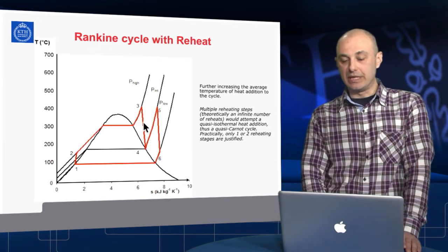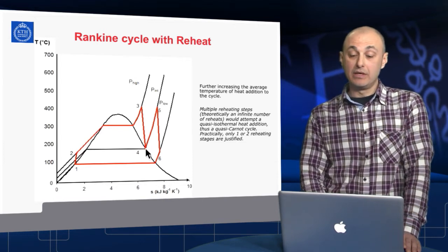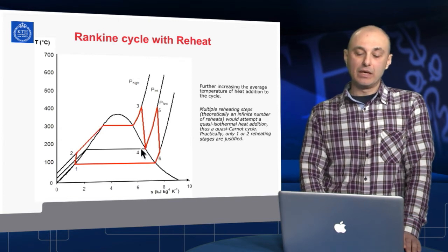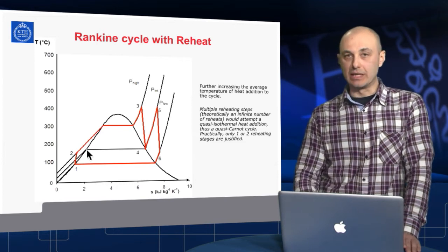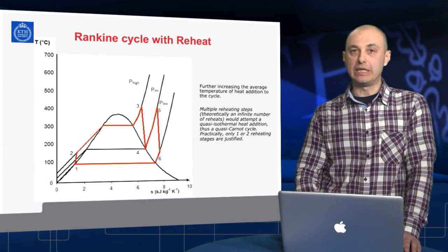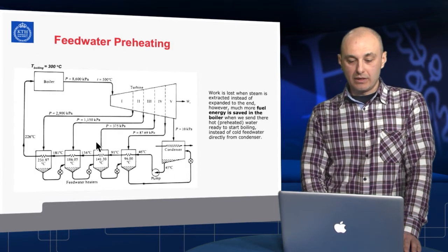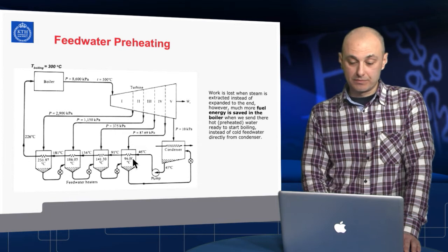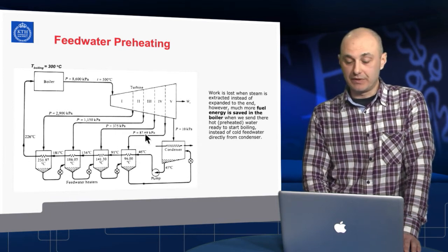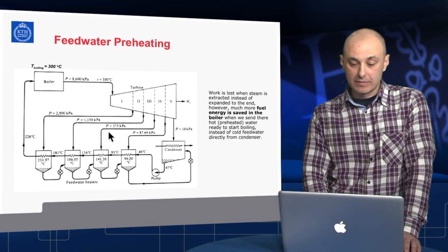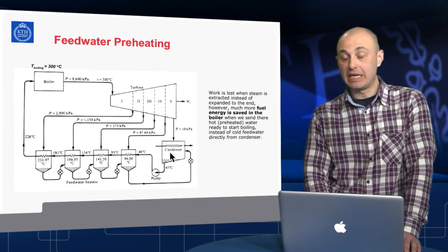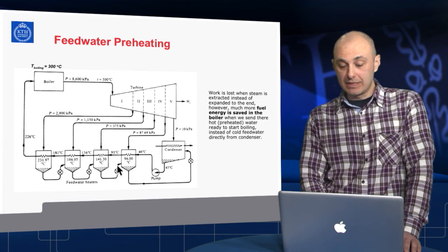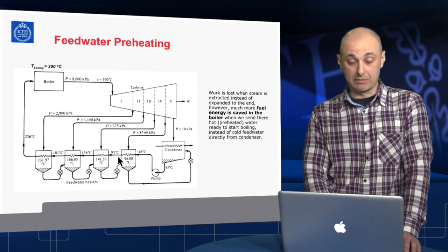And using this reheat diagram, we can imagine that after the reheat, we extract a certain amount of the steam and condense it to take its heat and use it for feedwater preheating internally inside the cycle, integrated heat regeneration. Here we have 4 steps of those internal regenerations of heat. Steam being extracted, condensing, and after that it has in some way to be recycled back, whether cascading down to the condenser or pumped immediately back into the main feedwater line, it doesn't matter.